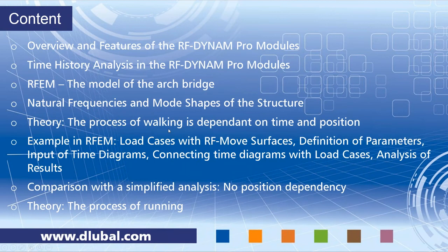So let's start with the content. I will first give you an overview and explain the features of the RF-DYNAM Pro modules. We will then have a detailed look into time history analysis and how this is implemented into RF-DYNAM Pro. We then already have a look into RFEM and the model of the arc bridge. I will show you quickly how this was done, and we will study the natural frequencies and the mode shapes of the structure. This is important to decide whether or not we have to consider dynamics and which mode shape is the most relevant one.